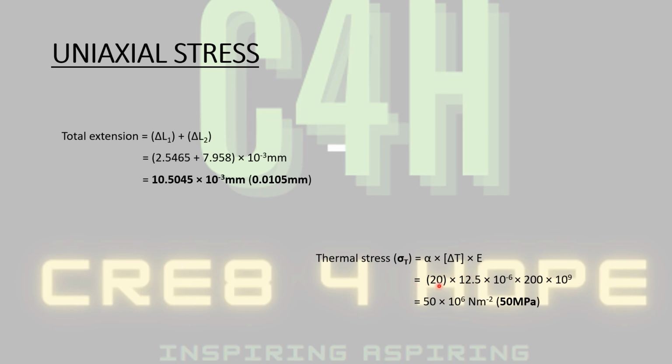So this becomes 20 times 12.5 times 10 to the power minus 6 times 200 times 10 to the power of 9, and this gives us a result of 50 times 10 to the power of 6 Newton per meter squared, which is the same as 50 megapascal.